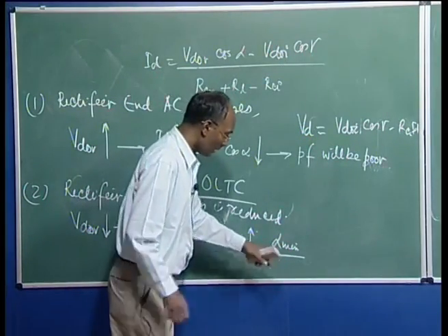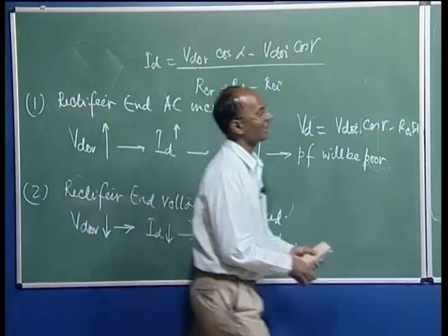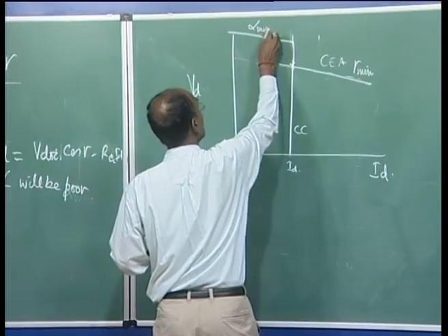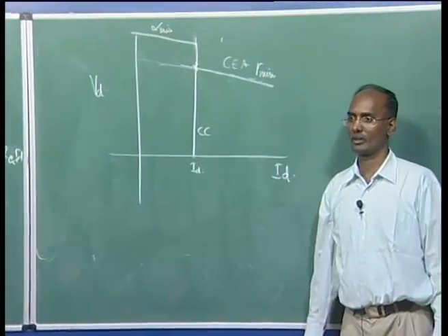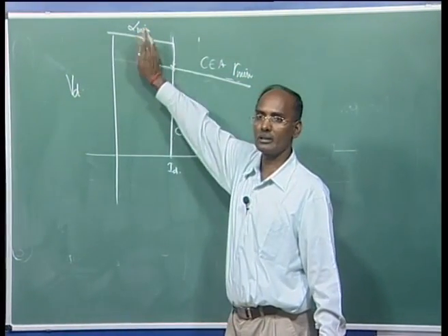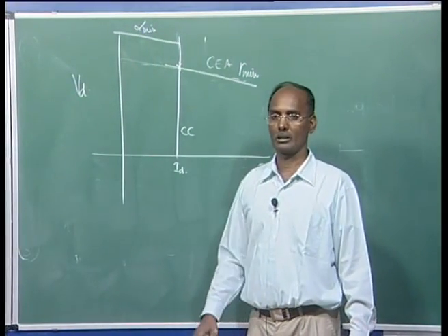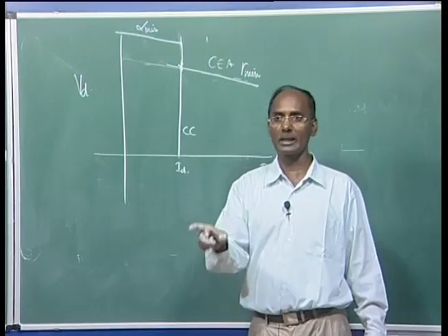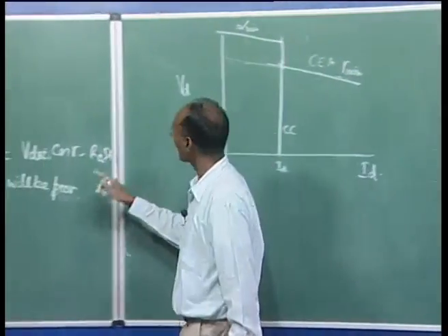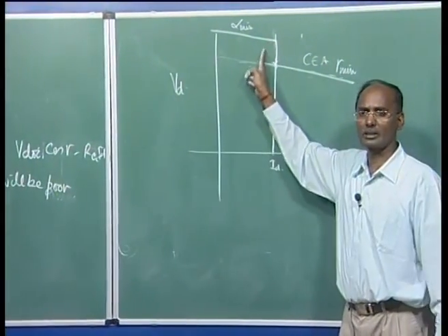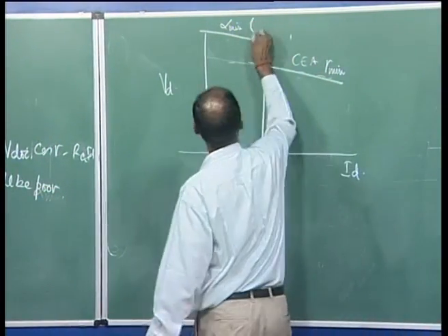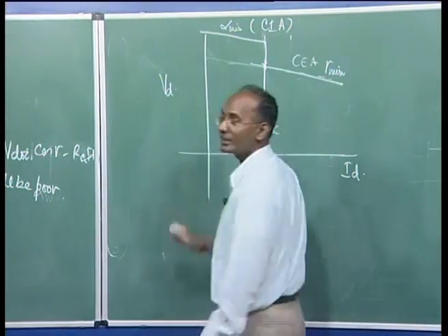So now you can see from there we have this characteristic here, meaning your value is here and it is hitting the alpha minimum characteristic. It is not possible here to maintain this, because the alpha minimum is hit, and now this will be stopped, that's it. Maybe your OLTC will take care, and suppose it is not taking care, then we will see another one will take care. So the alpha minimum characteristic is also given here because it cannot go beyond it. That's why here is CEA, here CC, and here it is also called CIA, that is constant ignition angle control.